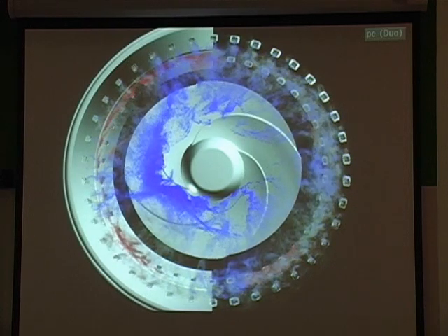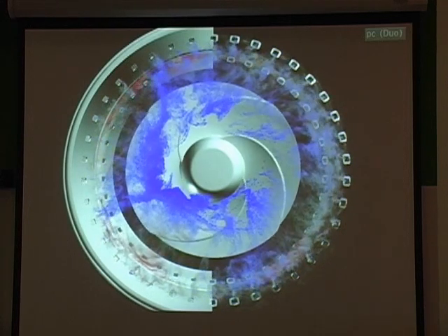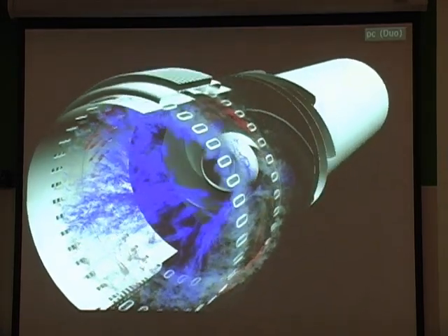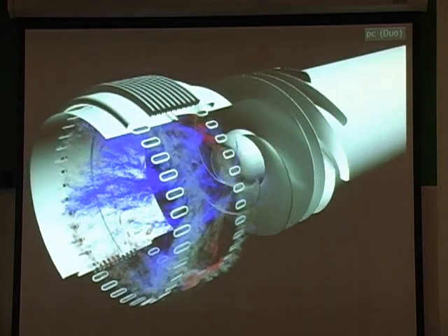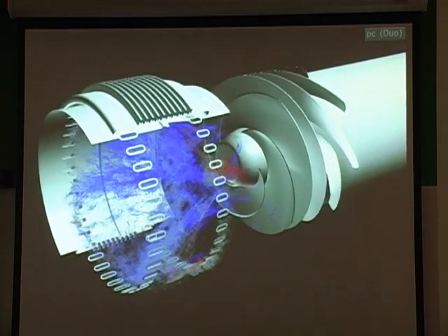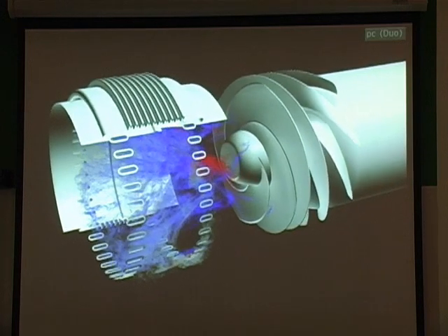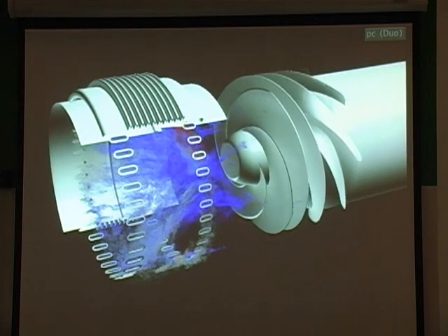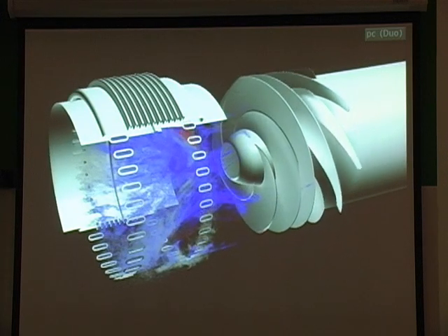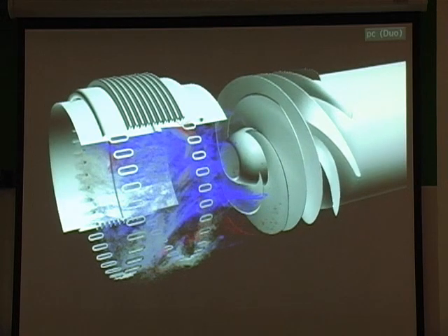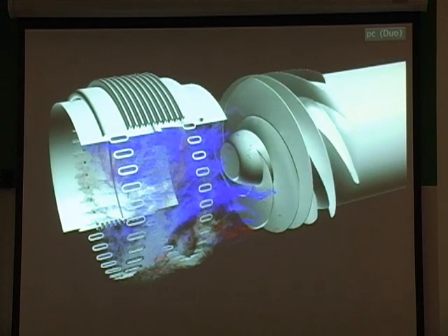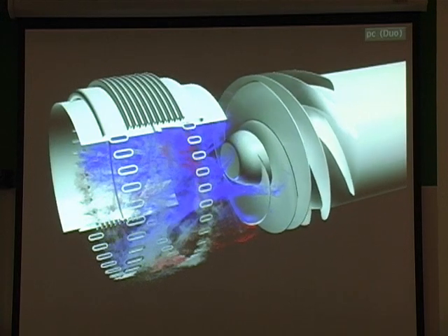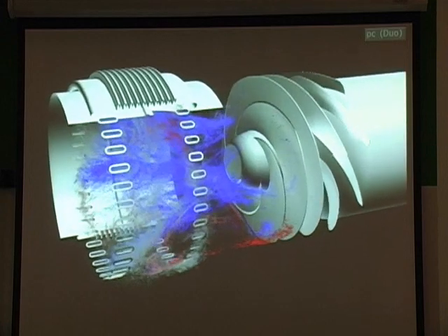And in general you can see that the impeller kind of pulls the flow forward and in, and you can see around the outside we get reverse flow. In general terms what's happening is that the flow has a lot of momentum, and it's actually kind of bouncing back off the outsides of the blades. You can see this reverse flow in these pods around the outside, and what that gives rise to is a kind of back and forth motion and a resultant pressure fluctuation around these holes, and that was fatiguing the metal, and in some cases that was even leading to cracks.